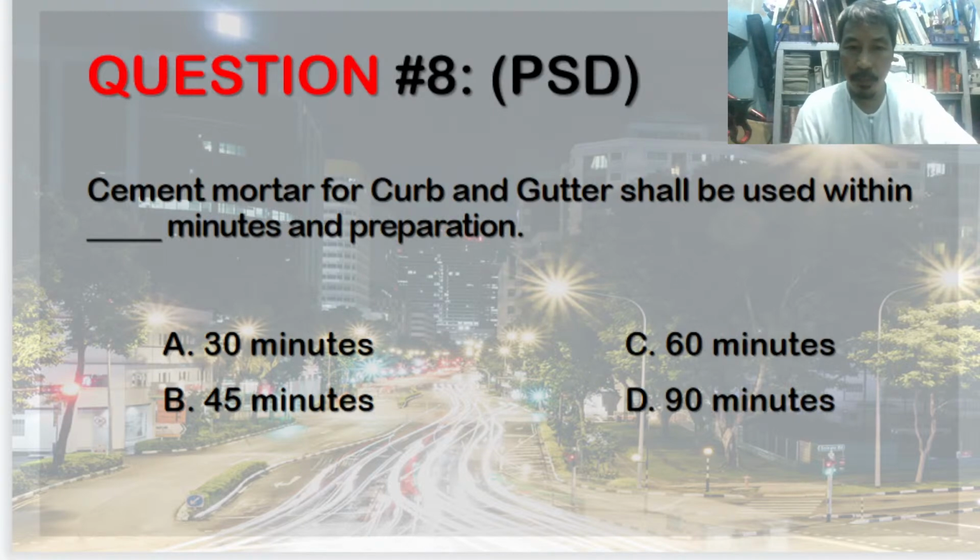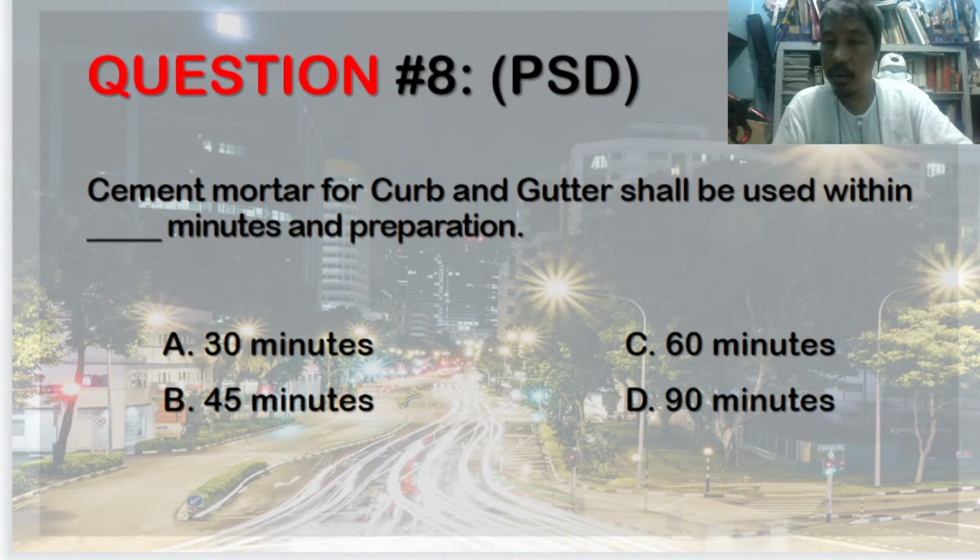After preparation, how many minutes must it be used within? 30 minutes, 45 minutes, 60 minutes, 90 minutes. For stone masonry, that is 90 minutes. For curb and gutter, that is 30 minutes. And for grout, that is 60 minutes.